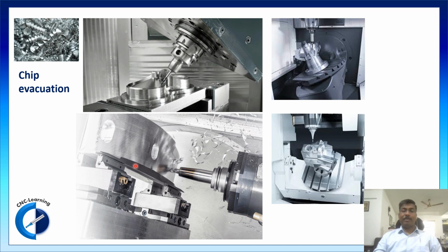Along with that, if you make use of coolant pressure and through coolant, then the chip evacuation will be the best in this case. Whereas in the other three cases, this is a tilting head and this is a tilting table, even this is a tilting table, the chip evacuation will not be as good as this.